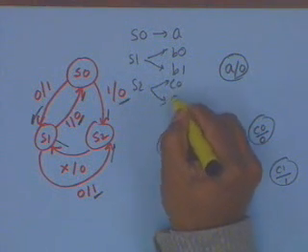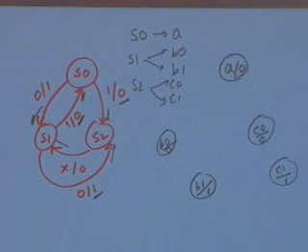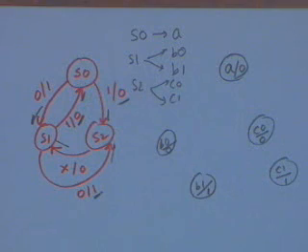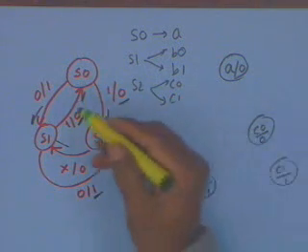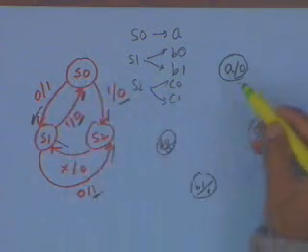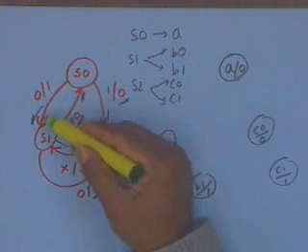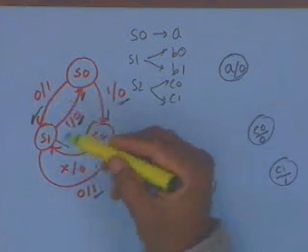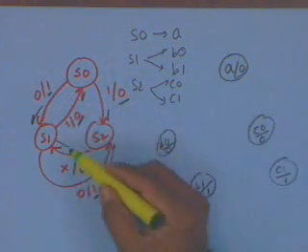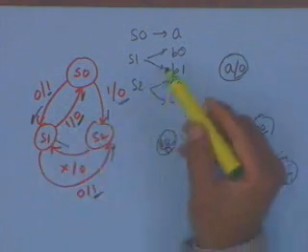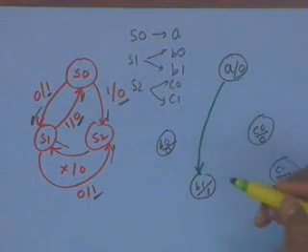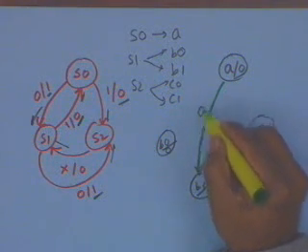The issue is how do I complete my diagram. Now let us look at state S0 and consider all the edges that are going from state S0. If I consider this particular transition from S0, there is only one state corresponding to S0, so this is a transition which takes an input of 0 and produces an output of 1. Because I am producing an output of 1, but this particular state S1 is being split into B0 and B1, I have to choose the particular state which actually produces an output of 1, and in this case this is the one which produces an output of 1.